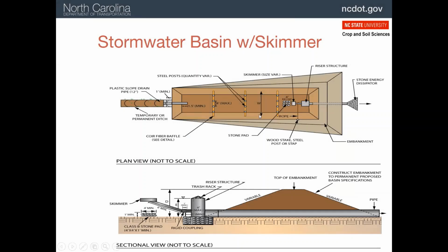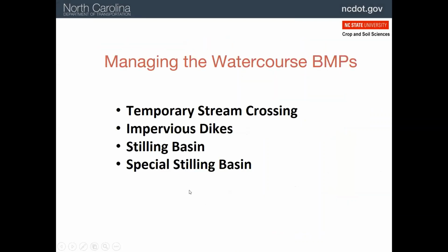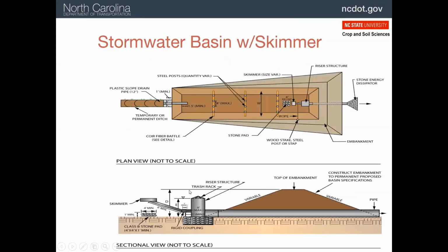And more views, bird's eye, cutaway. So essentially the only thing that we're doing different here is instead of having a temporary dam, we're having a permanent dam installed, putting in an outlet, which will be used later, and using that outlet temporarily with a skimmer on it.